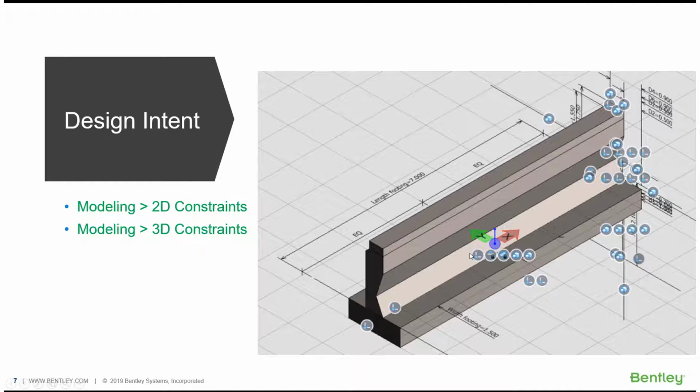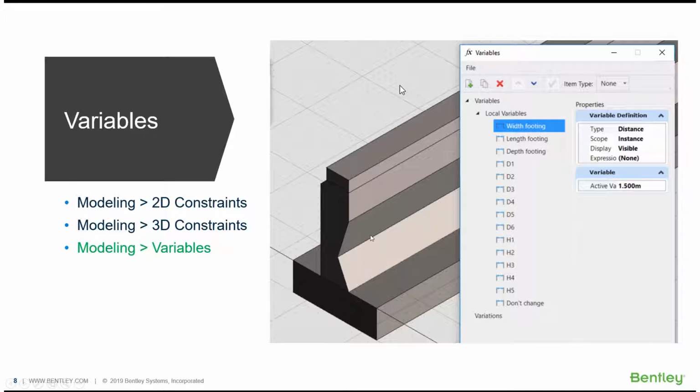And all these markers that you see, that's how you will create these parametrics and behavior that will represent the constraints, how the individual lines are going to behave when some of the numbers may change. Not only that, you can change numbers, but for your standard user, a number may not mean much, right? Because actually he wants to change maybe the height of the cap, the length of the cap. So, to any dimensions that you apply, you can also associate variables to it.